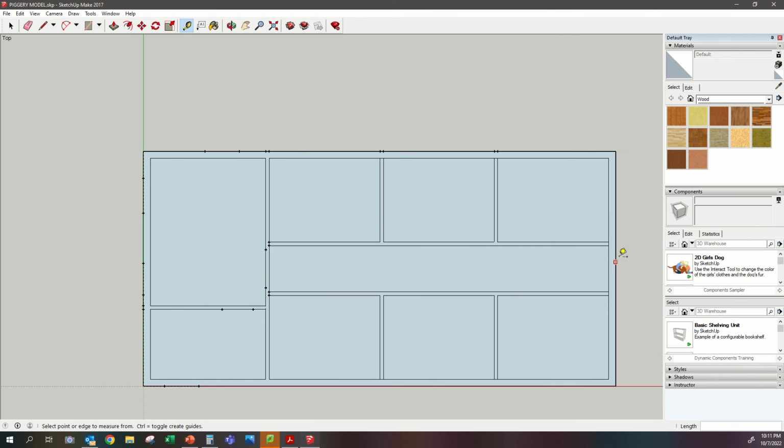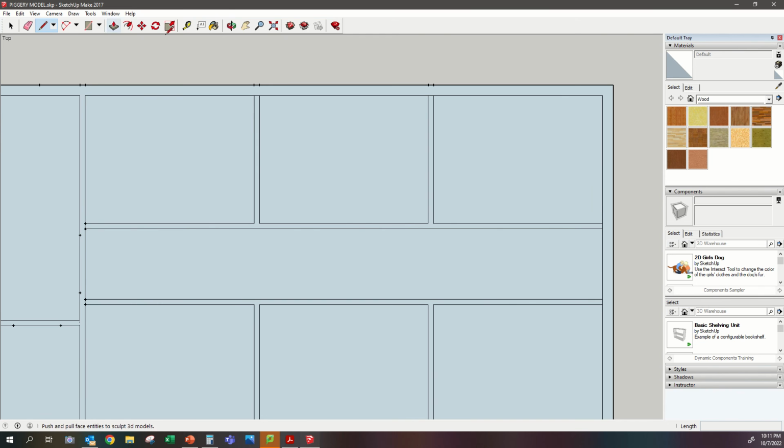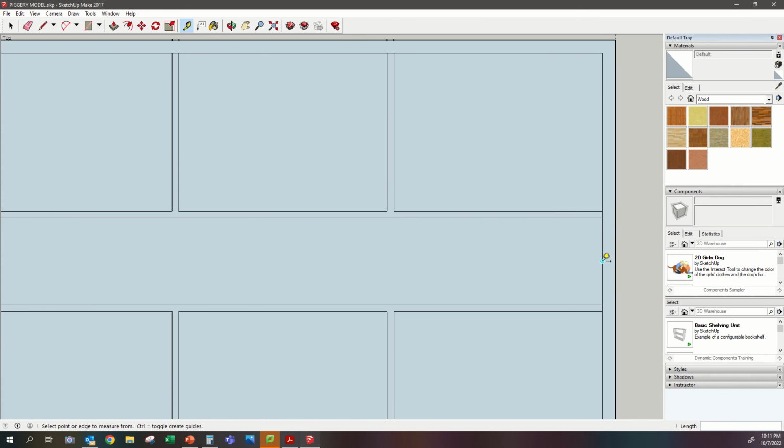And now we'll do the door on this side, the windows, the openings, and then the doors on the inside here; we'll also put in place measurements. Okay, so we're going to go across here, and let's just see if this will work for us. Can we work from a midpoint? Let's have a look. The door will be 900, so if I go 450 up, it's not working. Great. So what we're going to do is create an extra bit of geometry, and we're going to use that. So we're going to go from here, 450, enter.